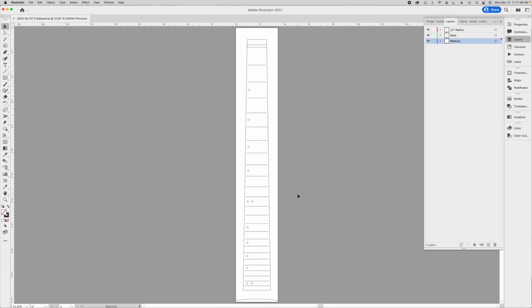However, wherever you do have a three-dimensional contour, and in the case of a fretboard, that's going to be the radius. In the case of a neck, it's going to be your back contour. And with respect to a body, you might have a carved top or comfort contours like a belly relief or arm contours. Anytime you have those angled three-dimensional shapes, you need to build a 3D model in order to begin the process of establishing the CAM strategy for those type of carvings. So that's why you need to have SVG and the 3D files that are necessary for this.